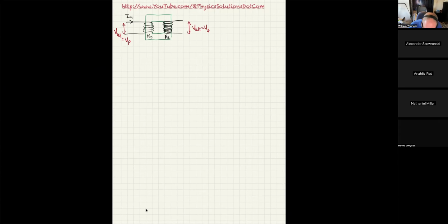But here's the big thing. We know from Faraday's law that E induced is equal to negative N d phi B over dt. If this belt buckle, which by the way should be made of, ideally, iron, which is ferromagnetic, and not only that, they would take the time to cut iron up into little thin plates, and then they would sort of glue them all together or laminate them, because the more breaks you have in the continuity of the iron, the fewer eddy currents you get, which can steal energy from the system.